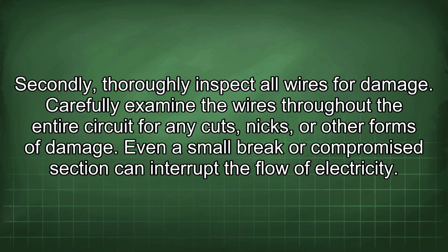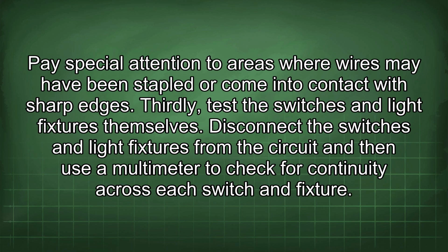Secondly, thoroughly inspect all wires for damage. Carefully examine the wires throughout the entire circuit for any cuts, nicks, or other forms of damage. Even a small break or compromised section can interrupt the flow of electricity. Pay special attention to areas where wires may have been stapled or come into contact with sharp edges.